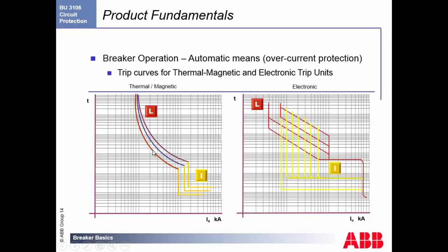However, if you know that the spike is going to be coming and you need a little bit more time to let the spike cool down or get to the motor so that the load warms up, you can pick the long curve over here, and you can see that your operation will keep on going at this spike for a longer time before the spike actually reduces itself, and then you'll keep on running for the life of the circuit.